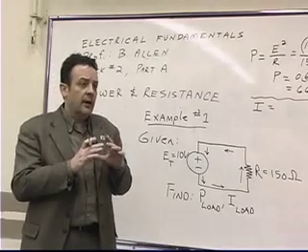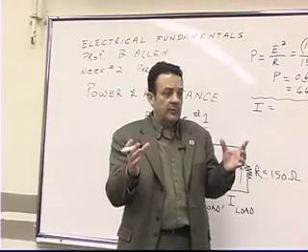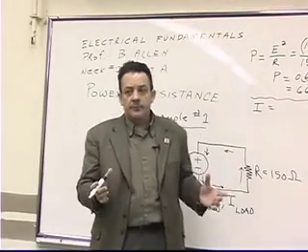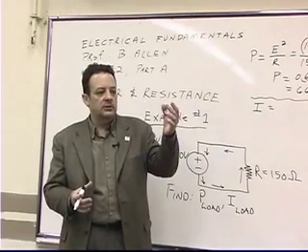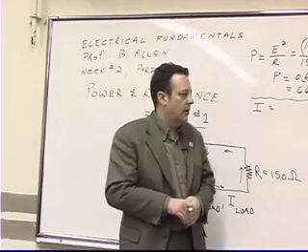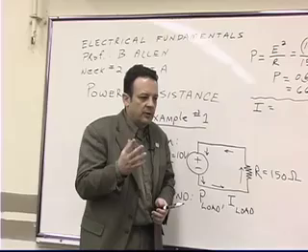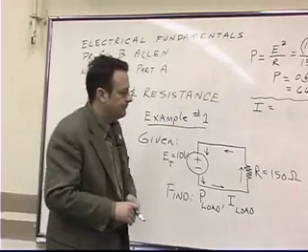Because if we undersize the wires, not only do they fuse in some cases, but what else can happen? They can arc and spark, and what causes? Right, fires are caused by arcs and sparks. So very important to understand current because it's a safety issue.